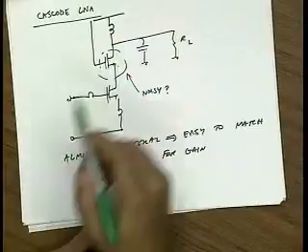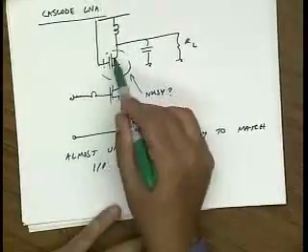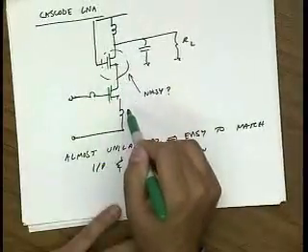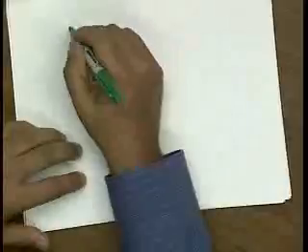And I would get a terrible noise figure. Well, that's not true, because this device, just like this device, is degenerated, right? This device is degenerated by this common source device, which looks a lot like a current source. Okay? So what I'd like to do is calculate the noise figure of a degenerated device.